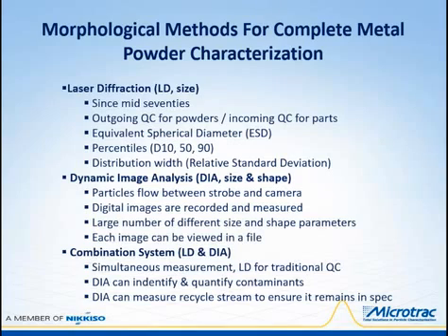In a combination system, one particle sample is circulated and measured simultaneously through each analyzer. This allows both the measurement of the industry's tried and true QC measurements by laser diffraction and the new shape measurements made by dynamic image analysis, which can measure and quantify the proportion of contaminants which affect the viability of all powdered metal parts. It also measures and reports shape characteristics which quantify whether or not the recirculating powder charge is going out of spec in laser melting and additive manufacturing.